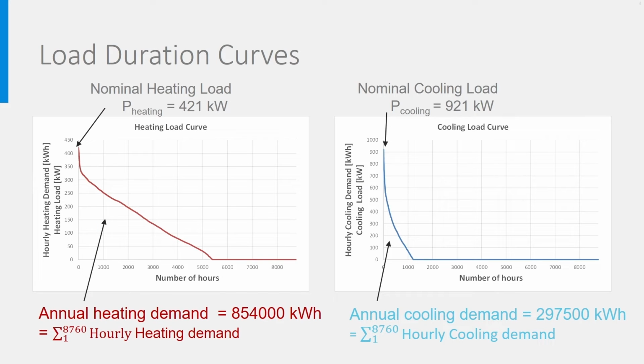To analyze these partial loads, it is useful to draw a load curve. It is very easy to do, you just need to sort all yearly data from the largest to the smallest one and to draw again the figure. I did it in Excel. You recognize the nominal loads, this time at the start of the curve.